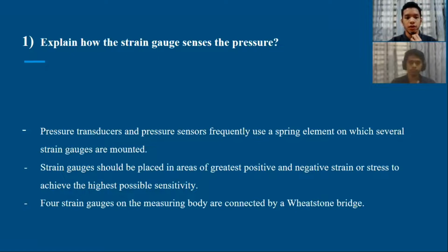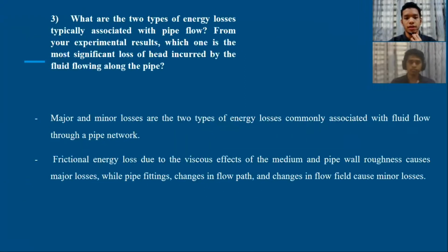The strain gauges on the measuring body are connected by a Wheatstone bridge. A measuring amplifier provides an excitation voltage to the strain gauges and acquires and processes the output signal from the bridge circuit to make the change in strain resistance visible. The resulting measurement signal can be processed by an industrial measuring amplifier before being sent to the programmable logic controller, PLC.